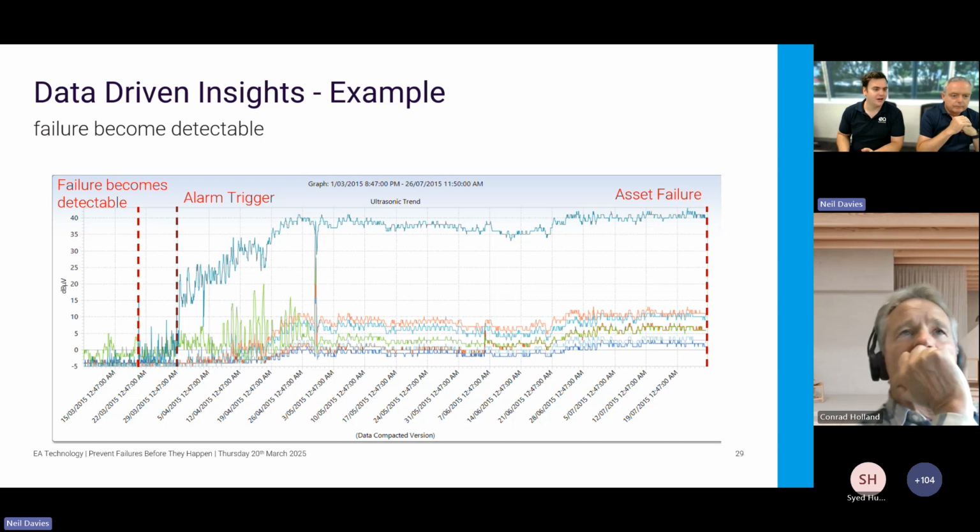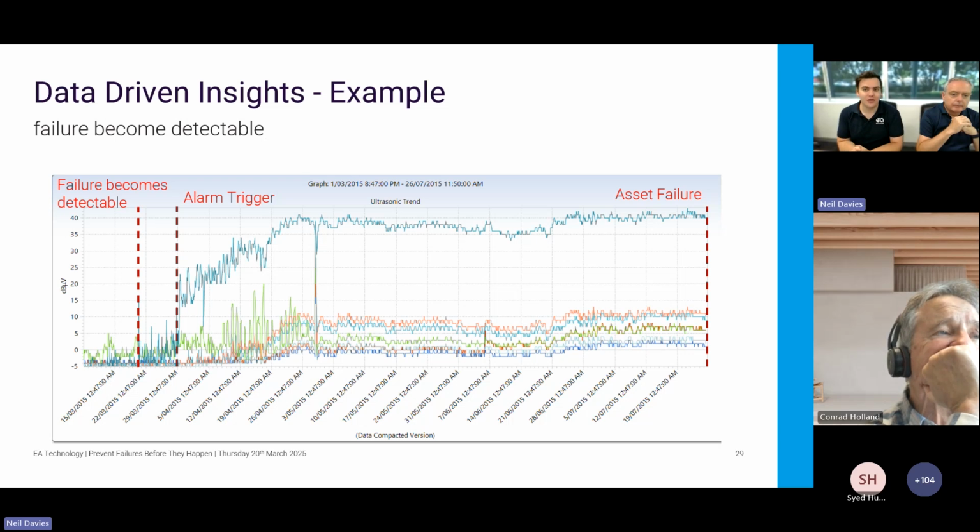Our alarm triggered a little bit later, once it reached a little bit higher level and got above the noise bar, but that's within, I believe, a day or two. From there, you had just between 3 and 4 months as the PD interval between when we detected it and when the failure physically occurred. And that is a very short time period, especially if you're doing point-in-time testing rather than continuous monitoring. And it's a really critical thing to think about.